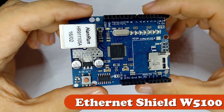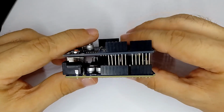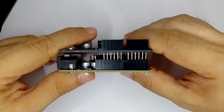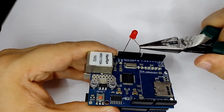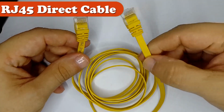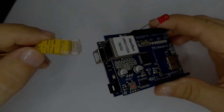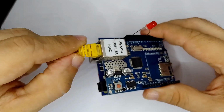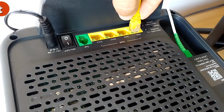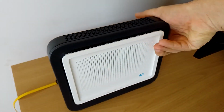In past videos we used a Uno R3 board compatible with Arduino, and a Shield W5100 board with Ethernet connection capability. We insert the Ethernet Shield on the Uno R3 board. We place a red LED between pins 8 and G and D. Using a straight-through network cable with RJ45 connectors, of sufficient length, we connect one end to the port on the Ethernet Shield board.